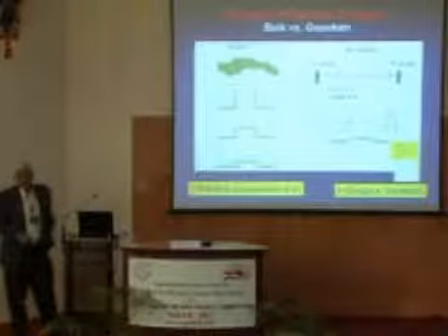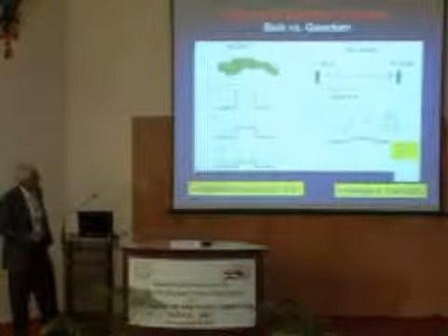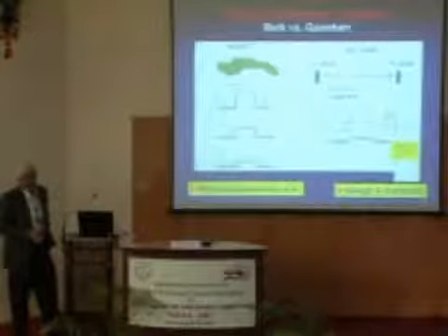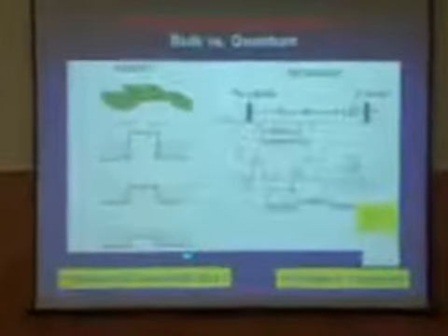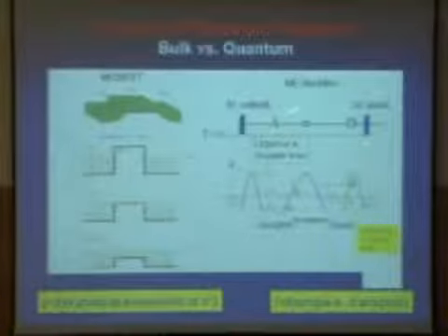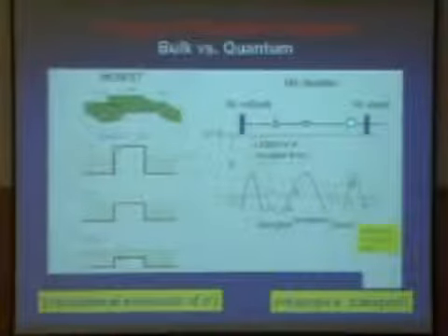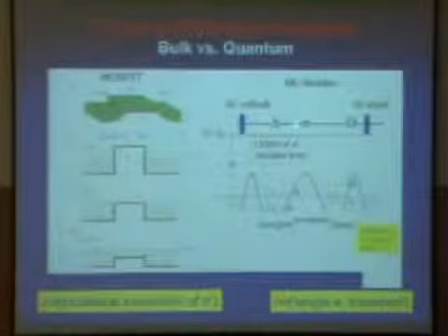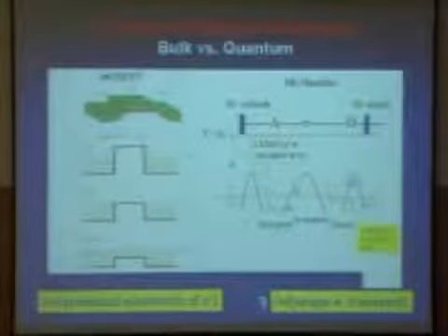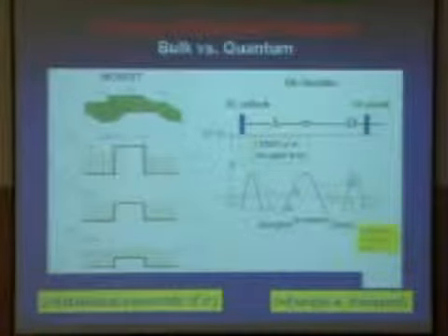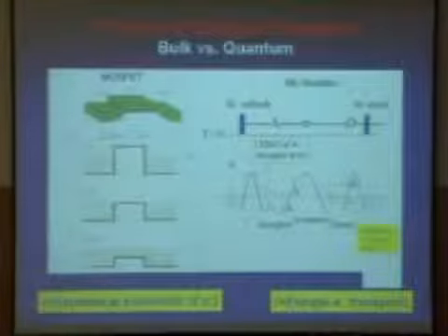Now let's look at bulk versus quantum transport, what we're dealing with. As you know, this is a MOSFET, the standard thing, and the current in this structure is basically a physical ensemble of electronic charge. But in molecules, if I pick up my contacts, anode and cathode, I have an acceptor and a donor, separated by a set of insulating molecules to provide a high barrier. So the current here is basically a function of single electron transport. The physics is going to change.